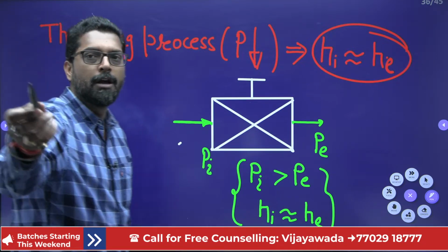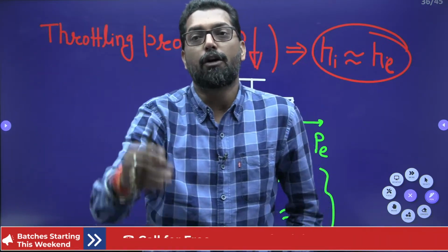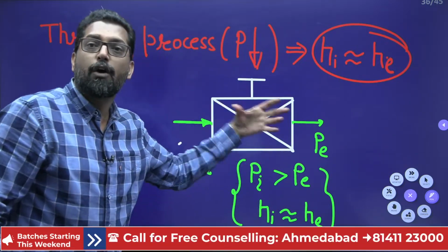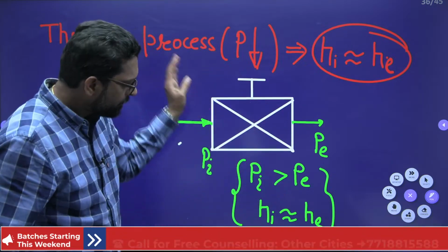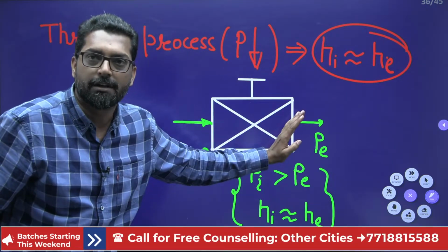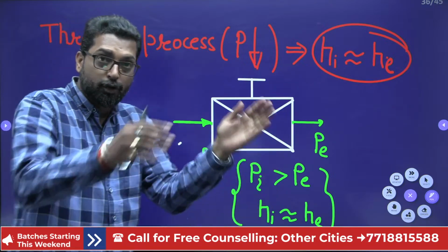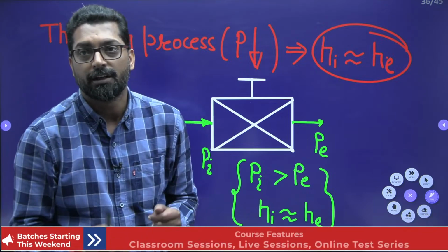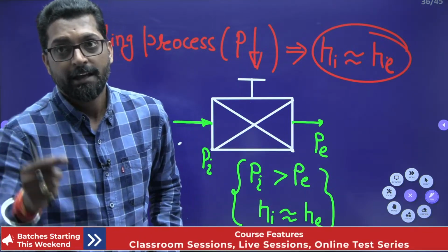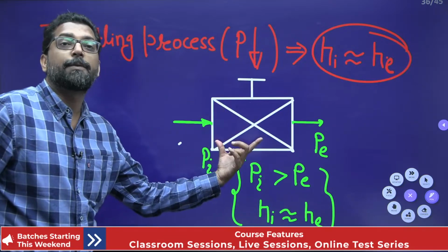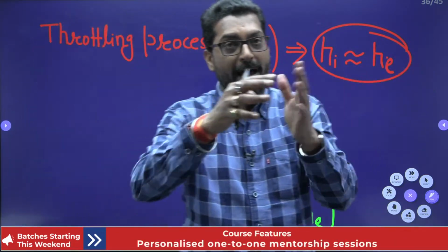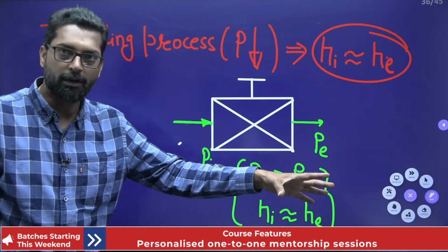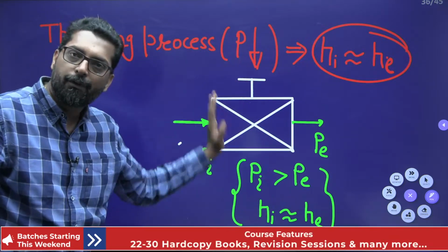Yes, we will discuss that next. Throttling and Joule-Thomson process are the same? Very correct. But what is the approach here? Pratik, we have to apply the steady flow energy equation. But the throttling in detail is in the context of the Joule-Thomson effect. Very good, Pratik. According to the Joule-Thomson experiment, we can achieve very different parameters for the throttling process, cooling and heating. But here we only apply the steady flow energy equation.